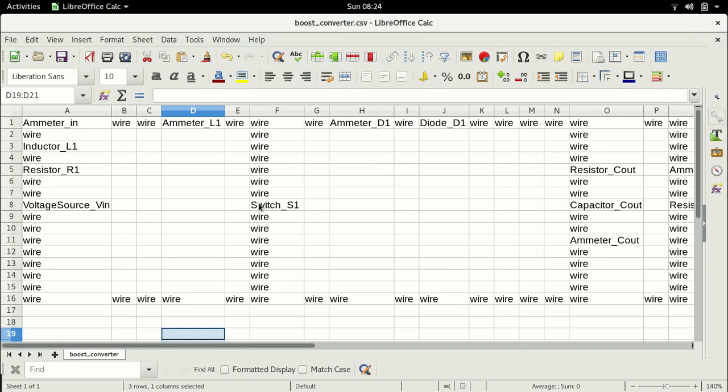Now, the reason why this huge amount of stress appears is because the switch is shouldering the entire burden of boosting up the voltage, right? The entire boosting up happens because of the action of the switch, and this is the reason why the switch takes the entire burden. That's not very safe, nor is it very efficient. Because remember, this switch, when stressed to such an extent, can be quite lossy, which means the efficiency of the system will be very low. Not to mention that this is very risky, and if it continues, you could end up with the switch and the system being damaged, right?